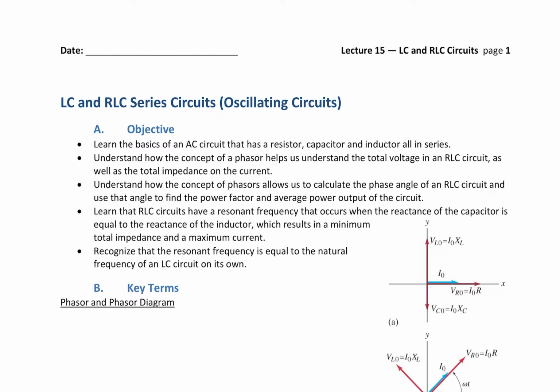First of all, what is a phasor and what's a phasor diagram? A phasor is a rotating vector. It rotates with an angular frequency omega. Now remember, omega is 2 pi times frequency. I don't want us to get too worried about it being a new type of vector. It's simply just a rotation. Think unit circle. It's very similar to ideas you've seen before, I'm sure.